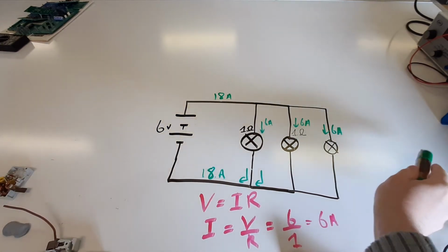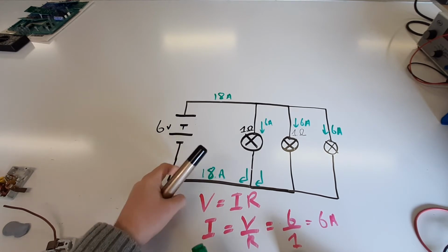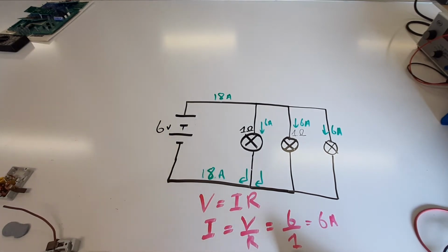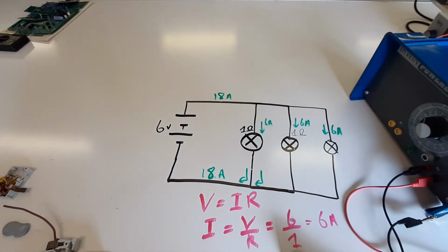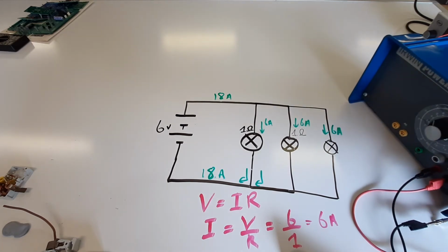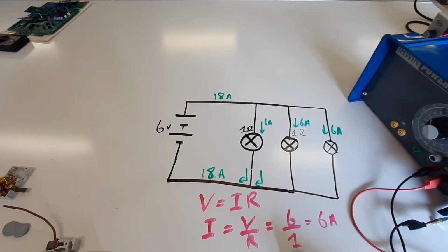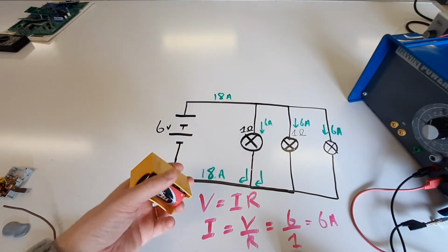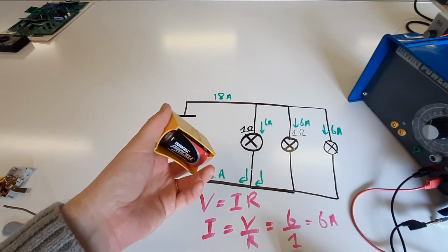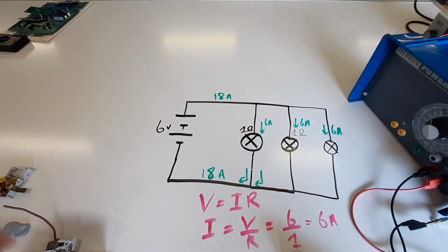The more light bulbs we add to our circuit, the more and more current we're going to draw off of it. Now, if you're using something like this, a power pack in a circuit, not going to be a problem, because this thing has a nice little trip button, which is going to trip if the current gets too great, so you can't get into too much trouble. However, if you're using one of these things, a cell or a battery pack, that's when problems can occur, because you start to draw too much current, things get too hot, particularly in this thing, and well, catches fire, maybe pops open, something like that. So that's a problem with Kirchhoff's law and parallel circuits.